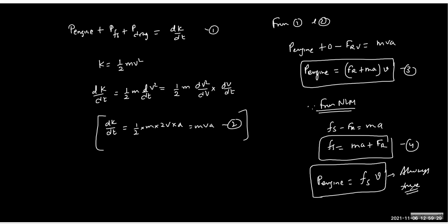If the air pressure in the tire is very high, the patch will become smaller because the high pressure tries to keep the tire round. That will decrease the frictional force, which is in a way good for driving on a straight road, but at the same time it will give you less frictional force also.